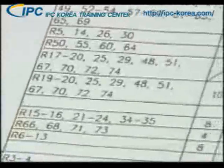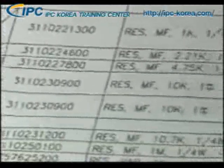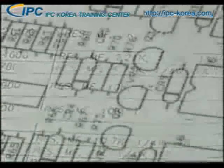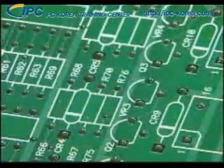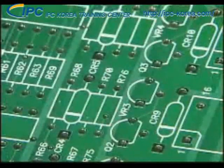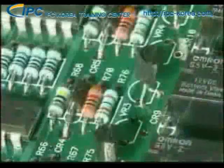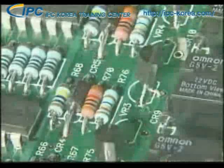It's important to remember that the bill of materials lists the components by part numbers and reference designators. The assembly drawing shows the location of the components by reference designator. And the component side of the circuit board is typically silkscreened with the same markings as the assembly drawing. This makes the component identification and insertion process more clear.